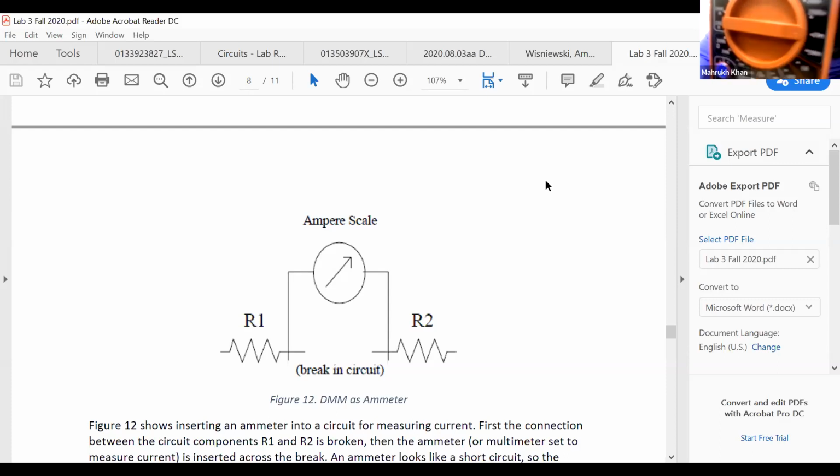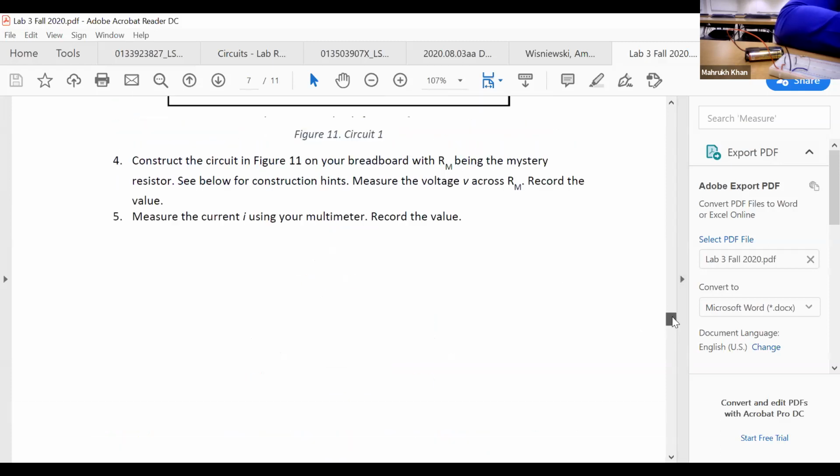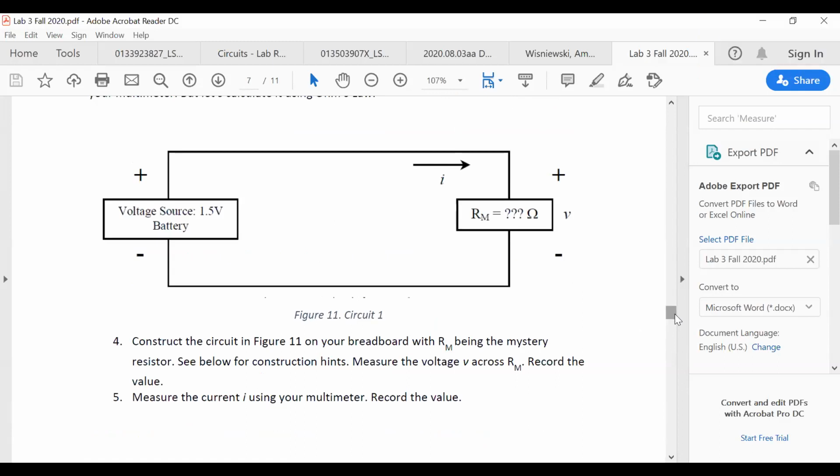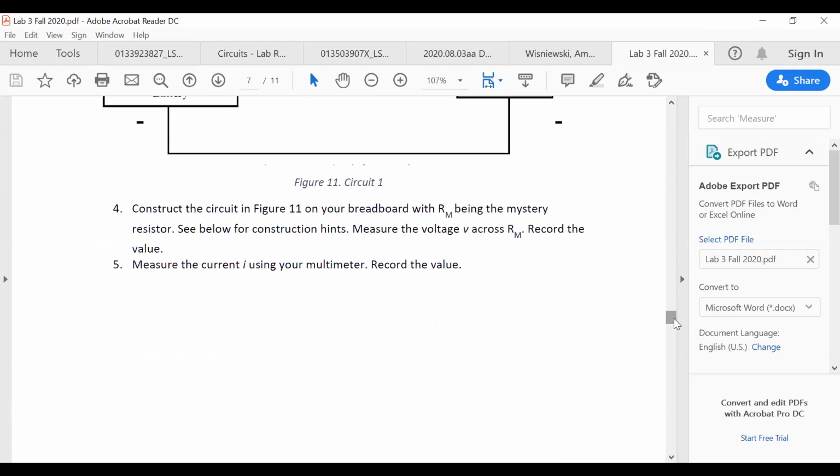Yes. So this is my multimeter, okay? Who was asking? Nicholas? Yes. Okay. So now I set it like that and record the value wherever you are getting. So let's say you were getting 2.9 or 2.8 volts, and then you were getting 2.9 current. When you divide voltage by current, you can get the resistor value, right? Yeah. So that's how you will try to measure the current.